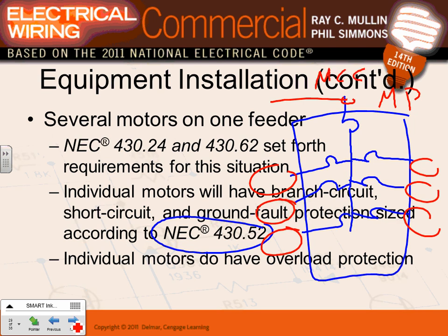The only thing in a motor control center, they add a controller here. Either way, when you size that feeder coming to it, and the overcurrent protection device, that's how you size it. The largest motor multiplied by 1.25 plus the full load current of all the others. And for the overcurrent protection device, suppose this was 100 amp, then this has to be 100 amp plus all the other motors. And then if it's not a standard size, you go down. We did the calculation for this, and we'll continue to do it, guys, when we do the calc. Make sense? No? Okay, so that's my calculation.